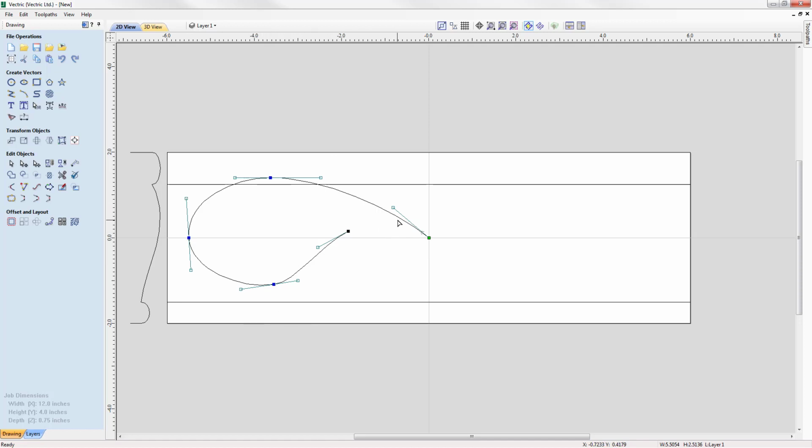So really we want to create a real nice smooth transition here. So then we're going to take this node here, and I'd like to align the handles in the Y axis, so we'll press Y there, and then we'll just again go ahead and just make the various adjustments. Might want to bring this span in a little bit, then we'll put that one back so that we're aligned in Y. I might just nudge that over a bit. And then just take this handle and bring that out, take this handle, just create a little bit more curvature there. Just click out just so you can take a look at how the part looks.